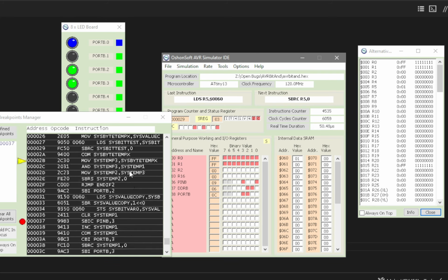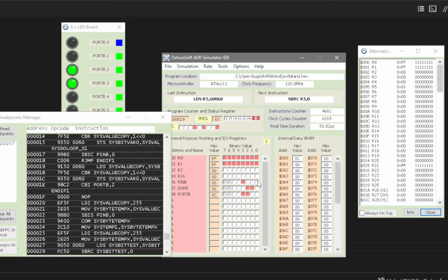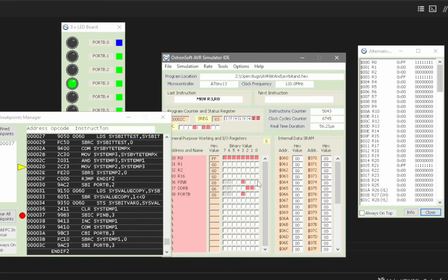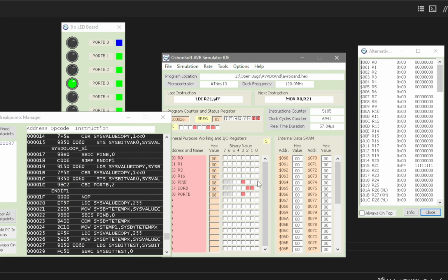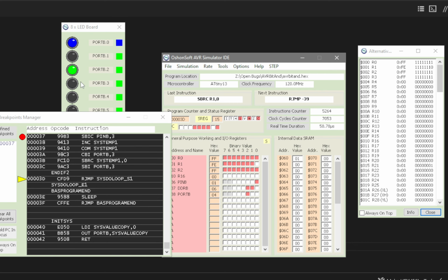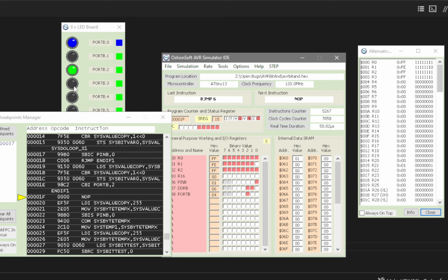So that was a breakpoint I put in this. If I toggle this off, all it's done is turn the LED off, but it didn't hit the setting of port B.3 because it only toggles it once. Click. It's now toggled it once. It's just about to set the LED high, or actually it's going to invert it. So there we go, it's just inverted port B.3. Great. So we've just adapted this code to prove what's happening.